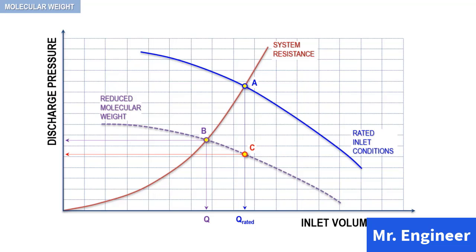If the compressor in this example operated with system resistance, it would search its new performance curve, so the dashed line, until it intersected system requirements. The result would be operation at point B as depicted here. Therefore, the inlet volume flow would be somewhat less than rated, and the discharge pressure would be slightly higher than calculated.